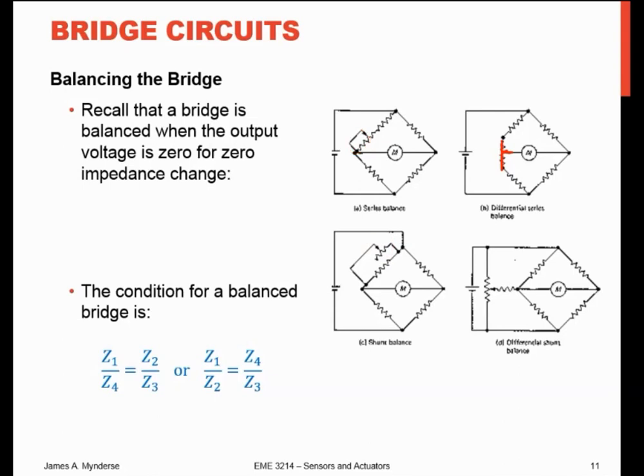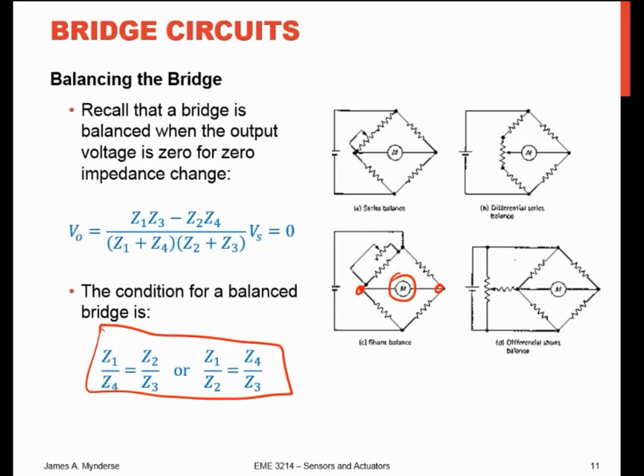And all of these things, you would start off by sitting with the bridge in its nominal case and adjusting those so that you get 0 voltage across your output points. And when that happens, you have one of these balance conditions, and both sets of equations are algebraically equivalent. Okay, and there's our equation for a balanced bridge where, yeah, you do the math.